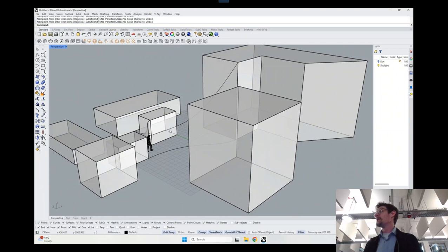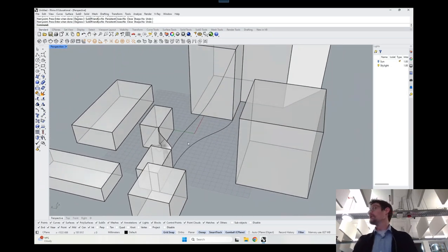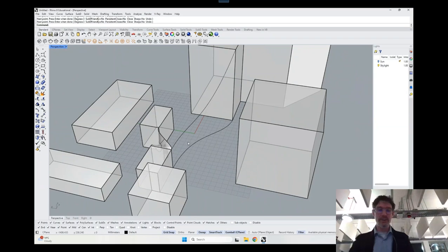There's a really good command. It begins with L. Remember it from a couple of weeks ago? Check your notes. You probably wrote it down. I've got two curves, or multiple curves, and I want to get a surface that goes through those curves. It is loft. The reason for checking your memory is because it's one of the ones which isn't obvious. It isn't make hull. It's loft. And why is it loft? Well, you just have to kind of learn it.